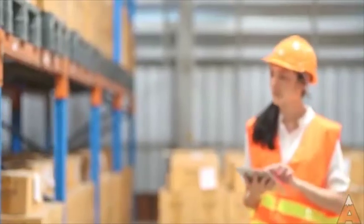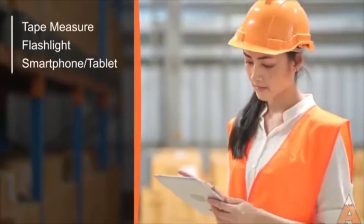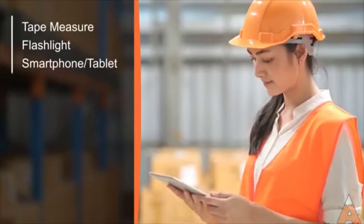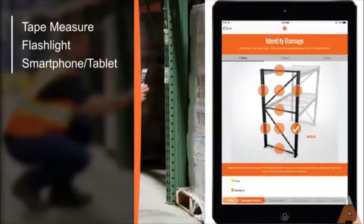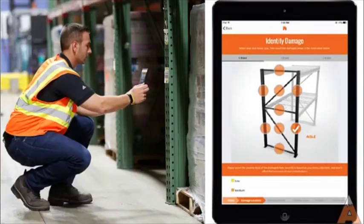Before starting the inspection, make sure to have a tape measure, flashlight, and a smartphone or tablet equipped with the Rack Repair app. The app is an easy-to-use pallet rack damage assessment tool that captures everything you need for rack evaluation and repair.